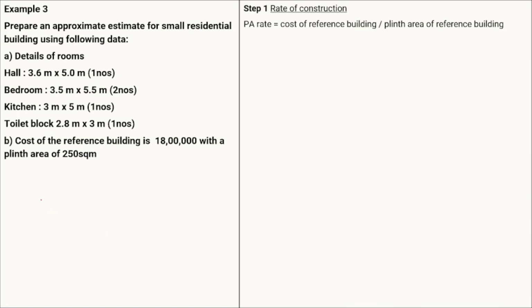Okay, now here there is no direct mention of the plinth area for our proposed building. Rather, the details of the rooms are given. So from the details of the rooms we can easily calculate the carpet area, and from the carpet area we can calculate the plinth area.